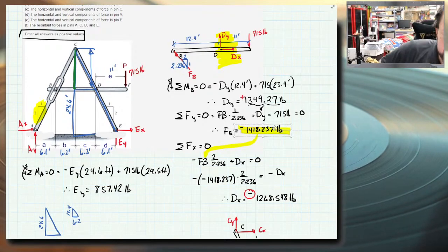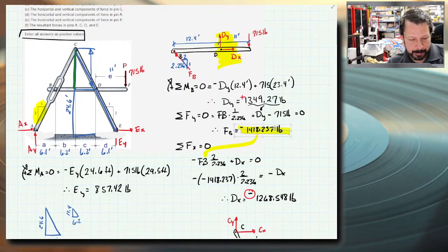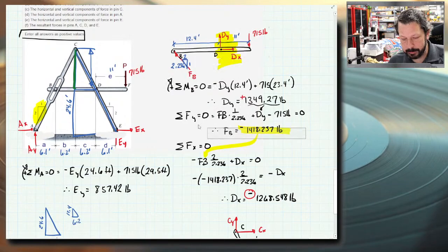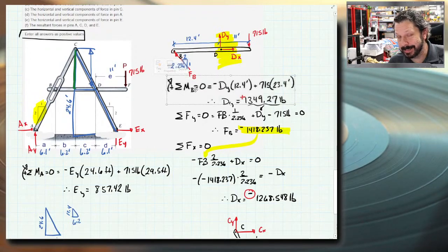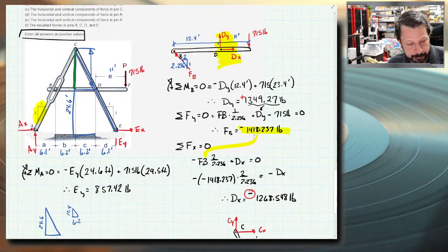So that's what would make it an easier advanced problem on an exam, only because it does have an easy solution. You could write just this one line, draw this free body diagram, and write a moment equation, but moments about D instead of about B, and you would get a value for the force at B.